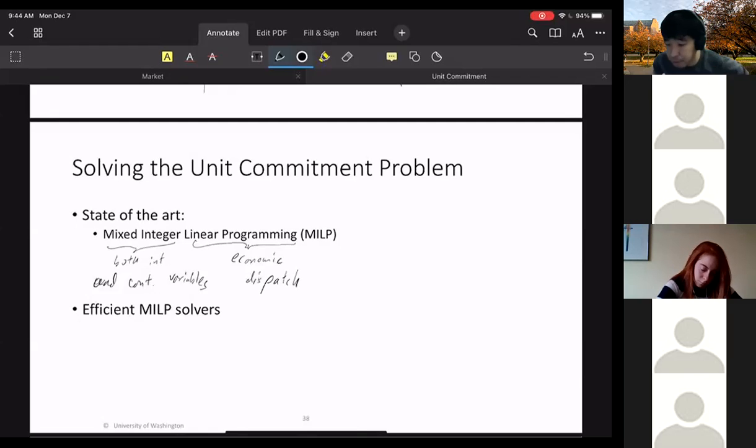Okay, so we're looking at the mixed integer economic dispatch problem. This is called a MIP, or MILP. There are various ways to solve a mixed integer problem, and quite a number of algorithms for this. None of them really have guarantees per se, because these are combinatorial problems. So there's no formal guarantee that you will be able to solve a MIP problem.